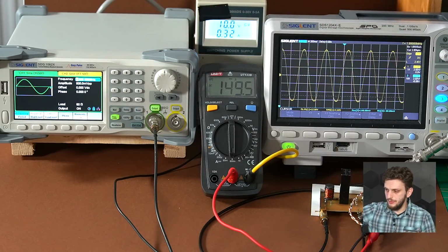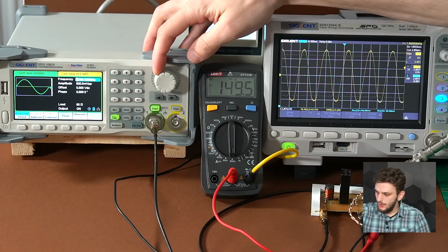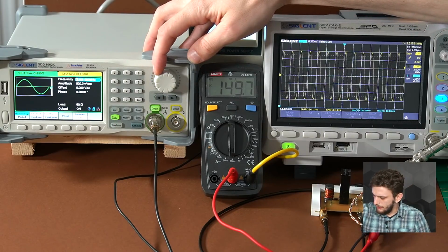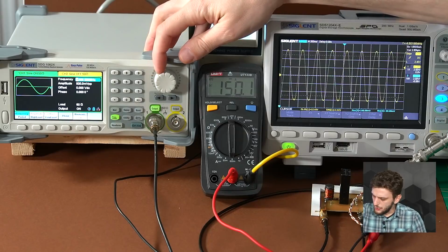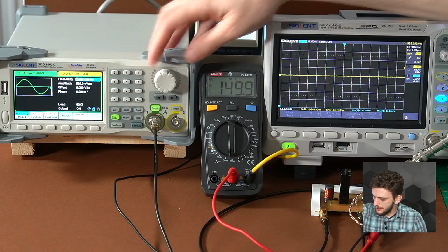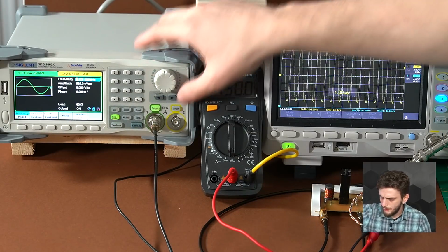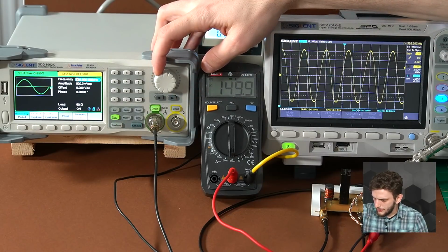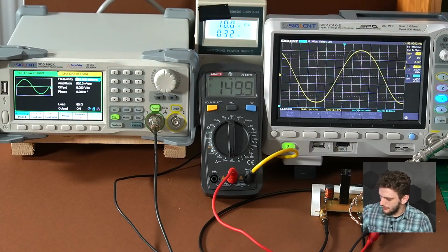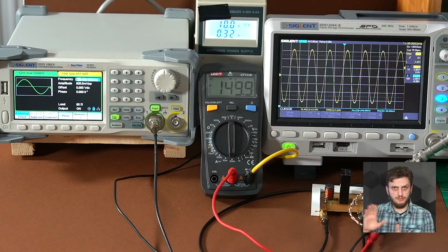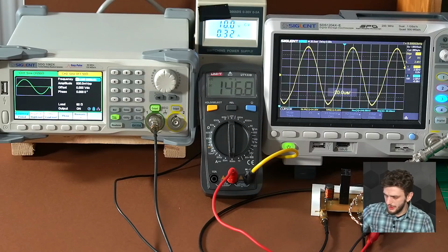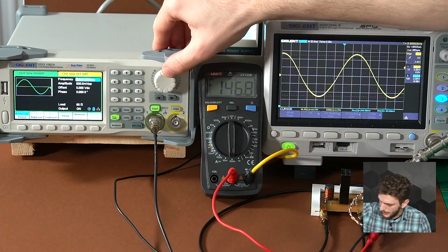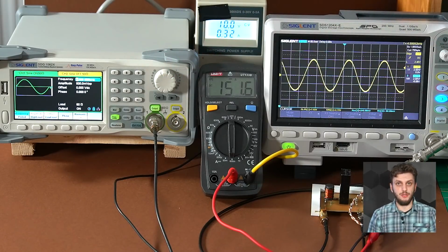The other thing that we can play around with is the input signal frequency. We can go up to 3, 4, 5, it's starting to decrease, so as frequency increases, we start to get a smaller signal, so this is at 5 MHz. But we can also go the other way, so 1 MHz, let's just zoom in a bit more, 400 kHz, 200, 100. We can see that we are still getting roughly the same amplitude, and we can go even lower. Maybe you can already hear it, it's at 10 kHz right now, and even lower, and now the amplitude drops a lot more.